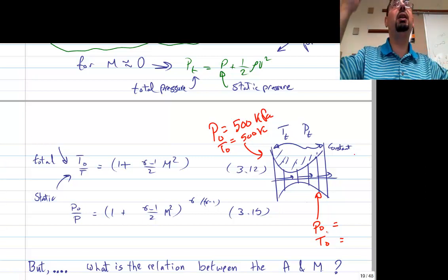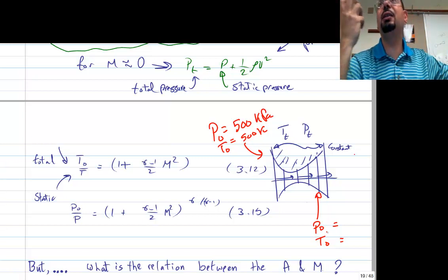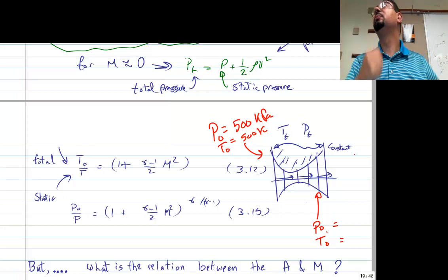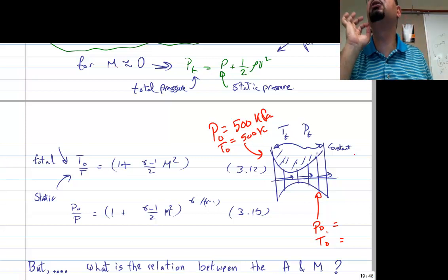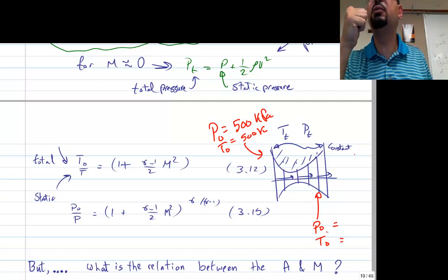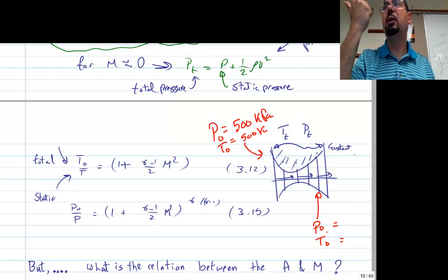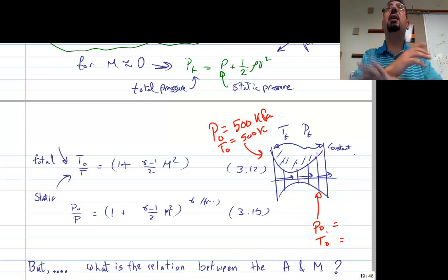This is really the essence of this chapter. If you don't get it, ask me again. Would that be because we're not actually adding heat, as the heat's been added prior to the nozzle? Excellent. Because this nozzle is isentropic. Isentropic means there is no heat transfer, adiabatic, and there is no friction on the wall. So nothing is being lost. The flow can speed up and its pressure drops or increases depending on whether it's subsonic or supersonic. It can do anything it wants.